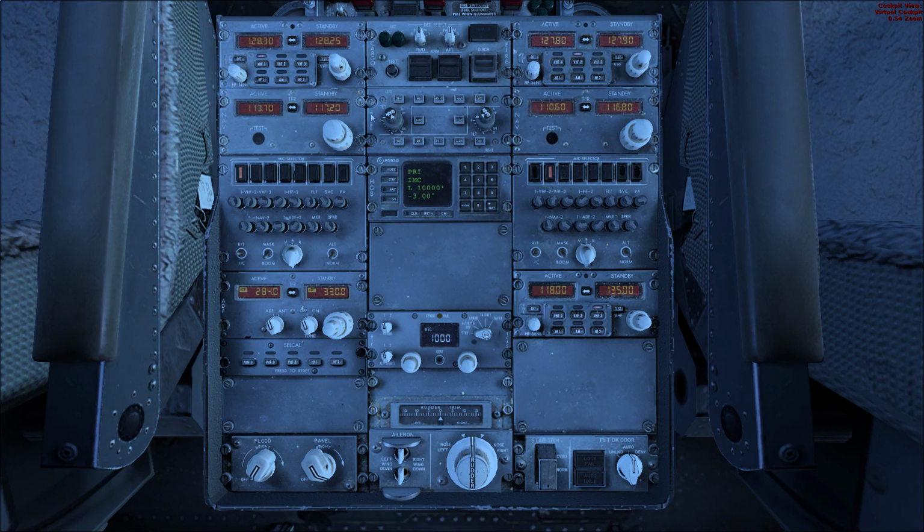and then down to the HDS panel and select whatever you like. Just set it to your needs. Now we set the transponder. So we don't have any ATC, we're just going to squawk 2000. Aileron and rudder trim is centered, and we can see that here on this tape. Now we need to check that the stabilizer override switch is on normal. That's on normal, that's fine.